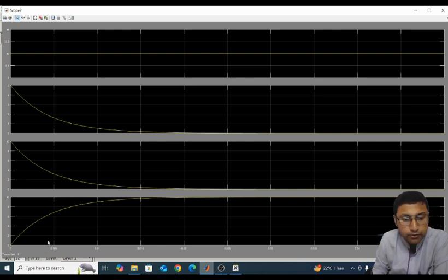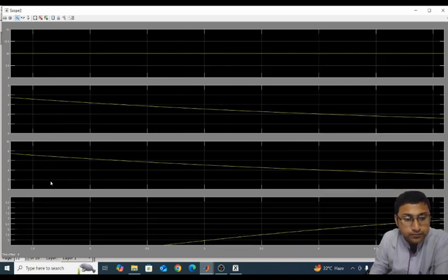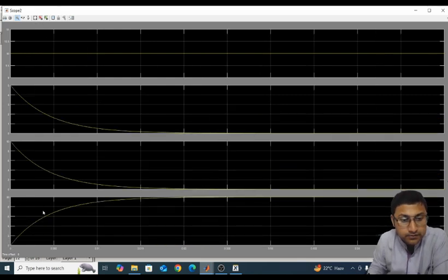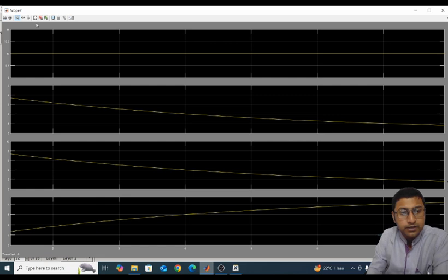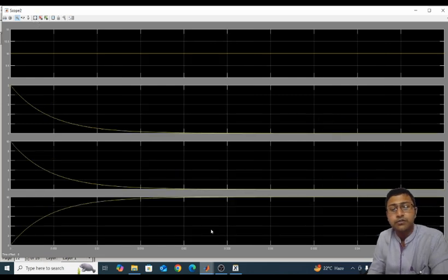So in 4.4 millisecond, it will reach the value of, if I zoom this section, at 4.4 milliseconds, suppose this is the portion, it reaches 6.32 volt. It just crosses the line of 6 volt, it is almost 6.32 volt. So from the graph the concept of time constant is also clear.